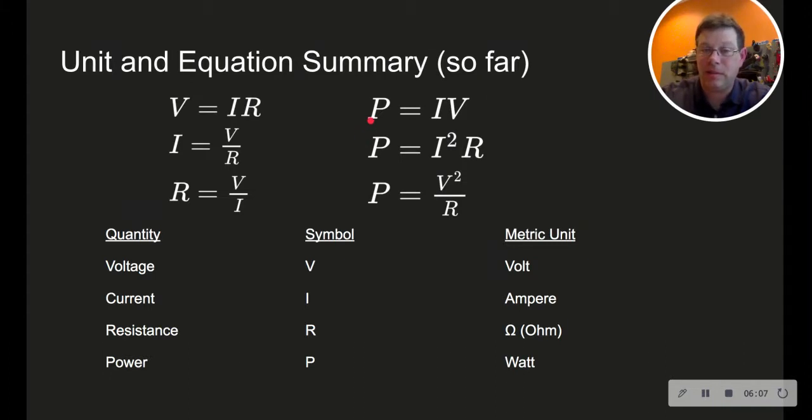For instance, since power equals current times voltage, if we take V equals IR, our original expression of Ohm's law, and plug that in for V, we get I times I, or I squared times R, for the power. And similarly, you can use the third form of Ohm's law to get P equals V squared over R. So these tell you the power that you would get from resistors. We say dissipated by resistors. We'll get to those words in a moment.